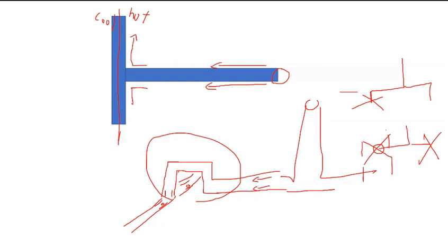And yes, a sudden change of thickness will cause temperature difference. So it's related to the sharp angle edge, but most normally it is related to the temperature distribution and causes high residual stress on the part.